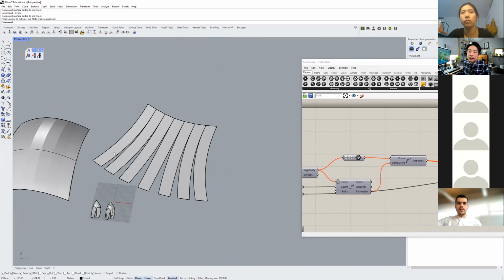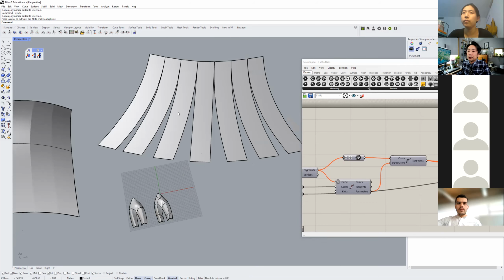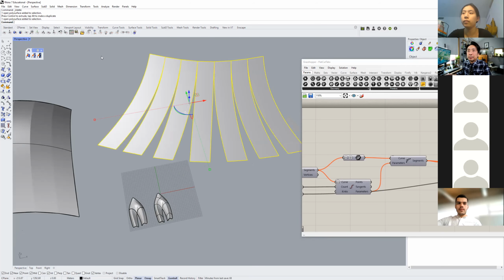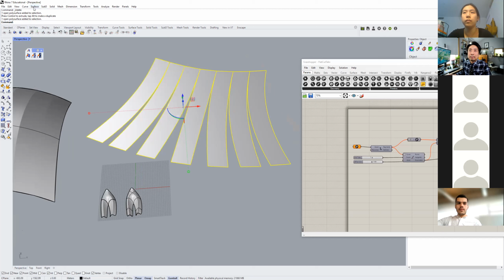The issue with this right now is when you try to glue these edges back together, it's an extremely thin edge. You'll have a really hard time merging them perfectly and then have a strong edge connection, right? You have basically a butt joint. A butt joint is not a strong bonding surface, right? So what you want to do is to create tabs. This file helps you create tabs very, very easily.